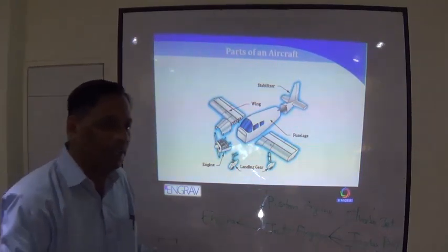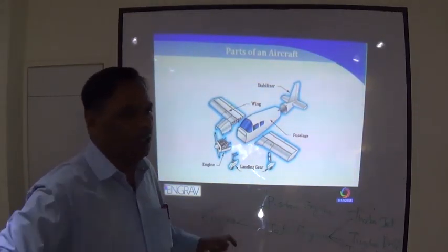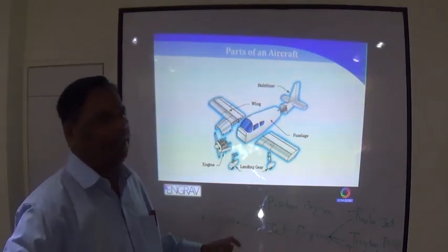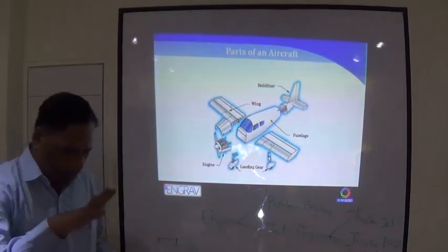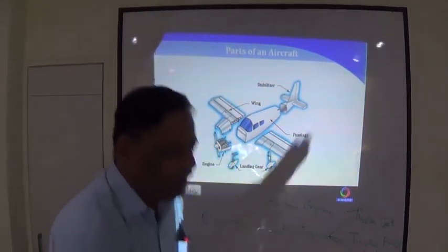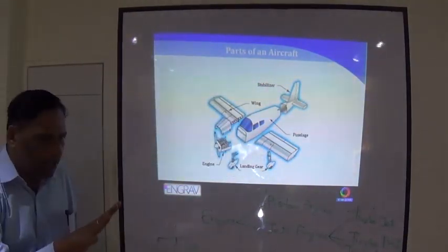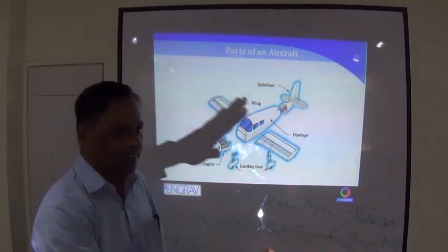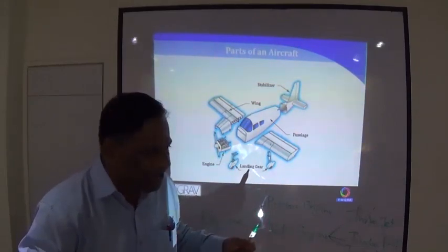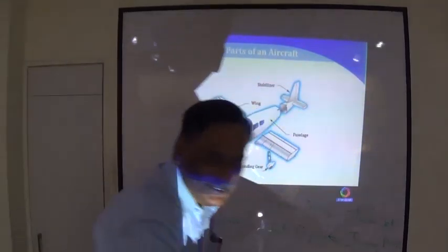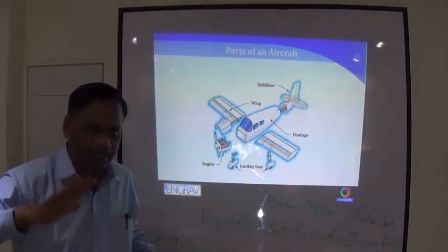So when you come to land, first they put the main landing gear down, and then the tail. Similarly, with a normal landing gear, you touch down on the main landing gear, roll for some time, then put the nose landing gear down. The aircraft geometry is like that. Unless the pilot does something very drastically wrong, he cannot land on the nose landing gear. The center of gravity is adjusted in such a manner.